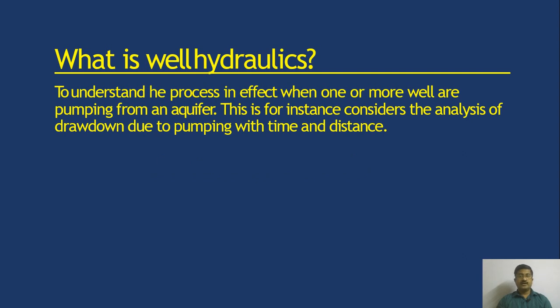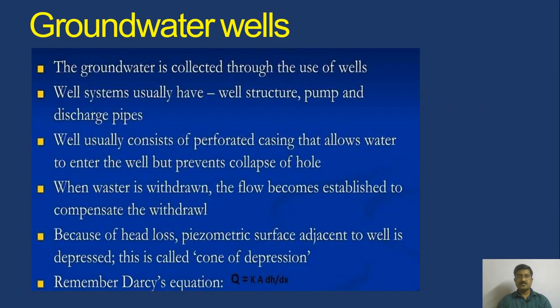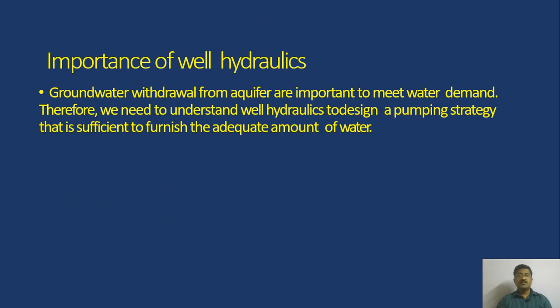What is well hydraulics? It is to understand the process in effect when one or more wells are pumping from an aquifer, for instance, considering the analysis of drawdown due to pumping with time and distance. Importance of well hydraulics: groundwater withdrawal from aquifers is important to meet water demand. Therefore, we need to understand well hydraulics to design a pumping strategy that is sufficient to furnish an adequate amount of water.